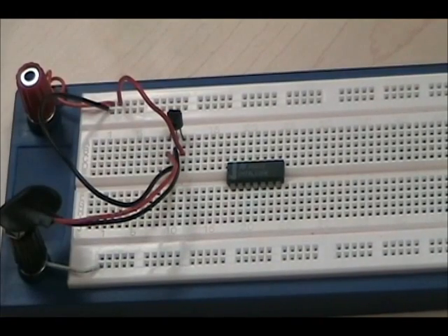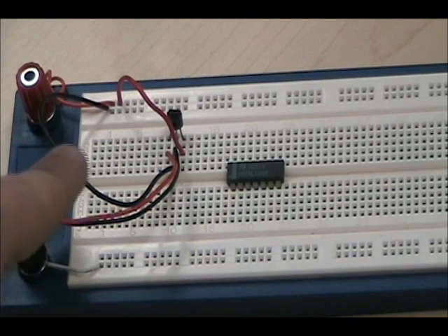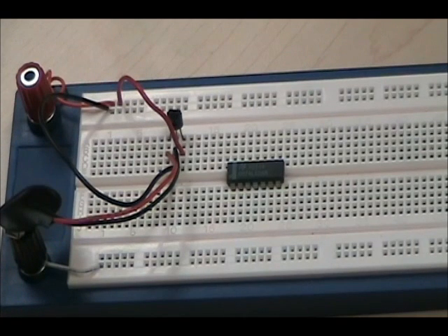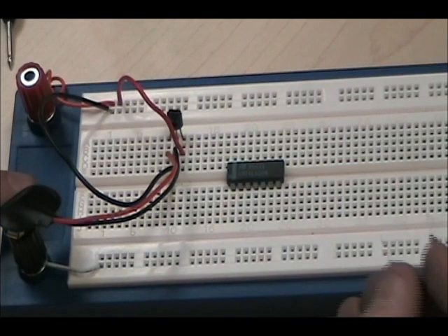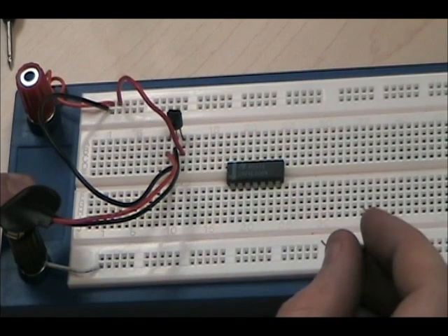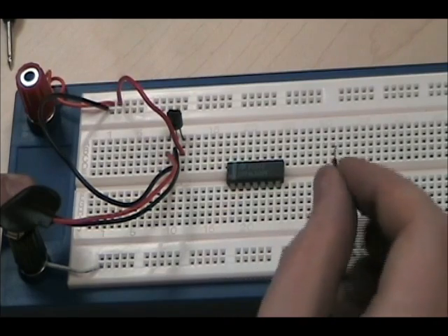So this is a 2-input AND gate, remember. I've got my power supply chip, my 78L05, hooked up. I hope you were watching this in order, guys, because I showed you how to hook up a 78L05 5-volt regulator. Remember, if you hook up more than 5 volts to this chip, you can very easily damage it. So first of all, we're not going to power up our battery, but first we're going to ground our chip.